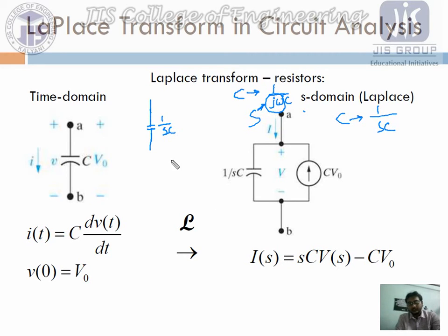Similarly, from this equation, if we consider the series circuit, there will be the summation of voltage, or for a parallel circuit there will be the summation of current, because for a parallel circuit the voltage will always be the same, and for a series circuit the current will be the same and the voltage will be different. So we have to change the equation in such a way.